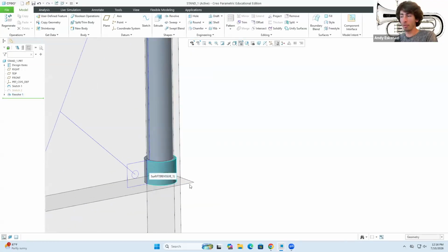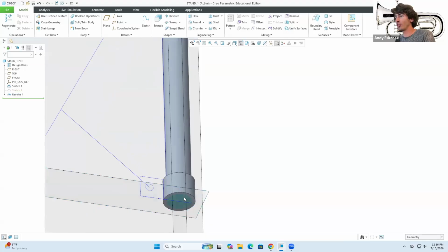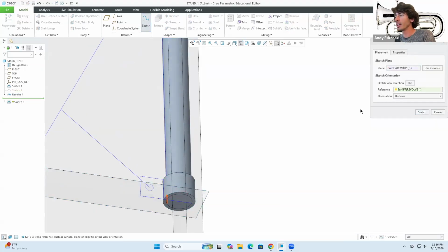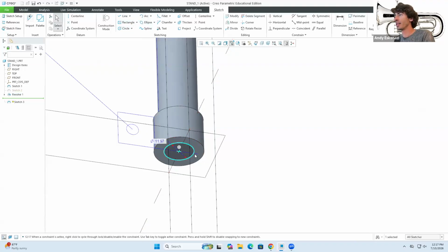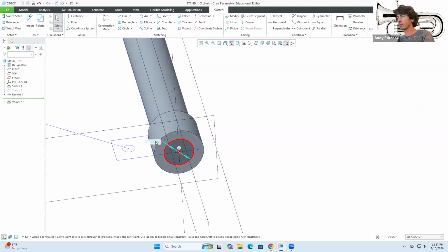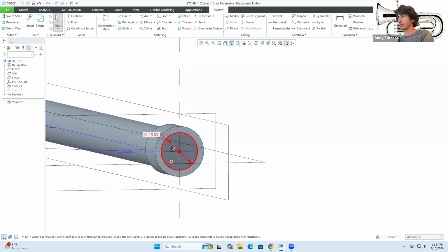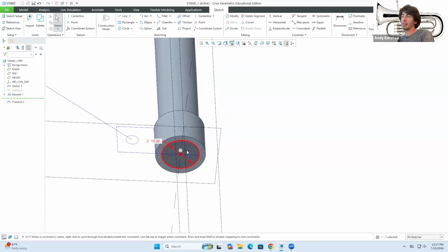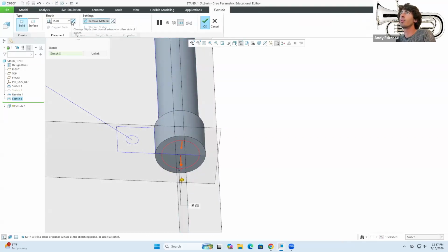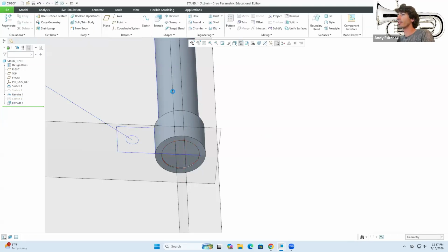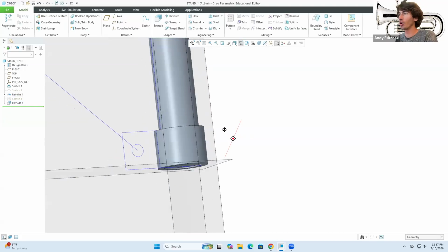Let's continue over with this piece. So in fact, to make it look a little bit more realistic, I can go to that face and I can say that I want a circle that will be, how thick did we make this? Was it 12? I don't know, I'll leave it as 15. I'll do just a slight removal of material by maybe 0.5. There we go. That way you can see that this is like its own independent piece.